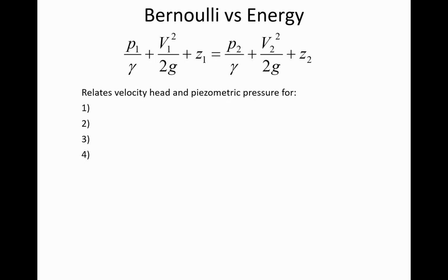So I've already mentioned that the first of those is Bernoulli's equation assumes that it's applying to an inviscid fluid, meaning a fluid that has no viscosity. And the reason why we made that assumption is that here in Bernoulli's equation, there's no factor that accounts for energy loss or pipe friction between 2 points. And so to make sure that we got into as little trouble as possible for that, we said that we'd assume that 1 and 2, these locations, are relatively close together. Because the closer together they are, the less likely that there's going to be some friction losses that dramatically change the pressure compared to what Bernoulli's equation would predict.